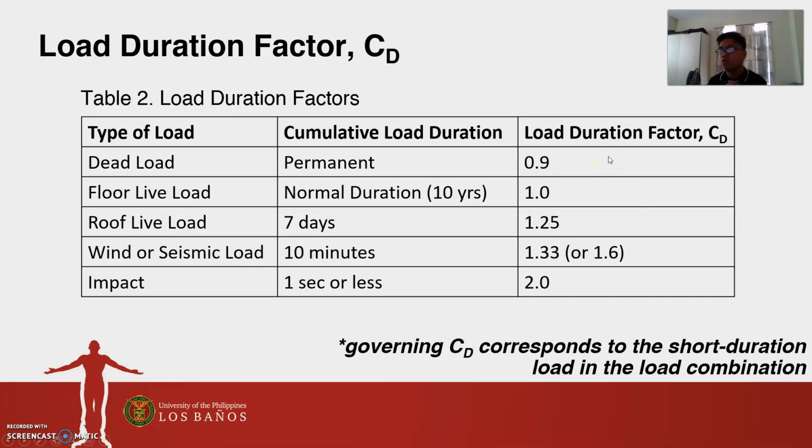Let's say you have a load combination of D plus W. What would be your load duration factor? That would have to be 1.33. Okay, that would govern over the 0.9 for dead load.